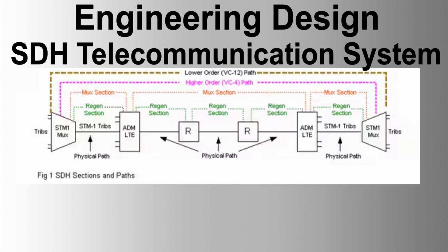50% spare storage capacity, memory and hard disks, under operation, for all servers and workstations after installation of all application system software. 50% additional storage memory, upgradable space available for future hot plug upgrades. 100% spare software license capacity available for all application system software installed. Additions of workstations and consoles ready to configure and use without the need for additional licenses.